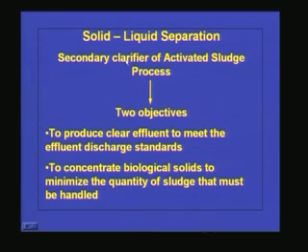Now, we will talk about the solid liquid separation process in an activated sludge process. We have seen that in activated sludge process, unless the solid liquid separation is there, we cannot call it as a treatment process, because in aeration tank only the conversion of soluble COD or soluble BOD to colloidal solid or colloidal BOD is taking place, because the organic matter present in the system is getting converted to new microbial cells, and that new cells will be remaining in the system.